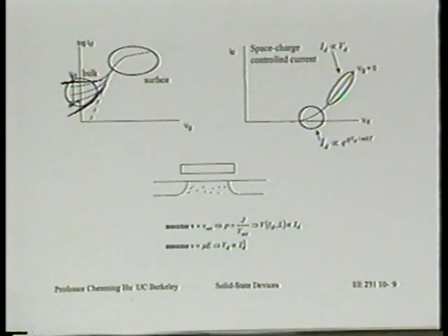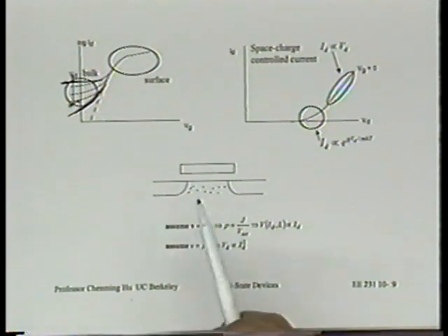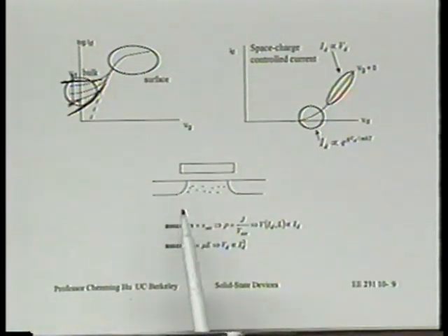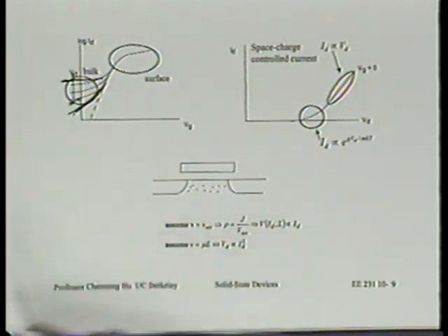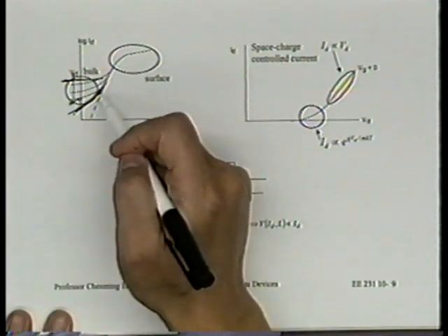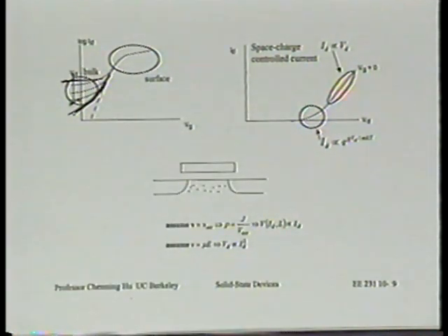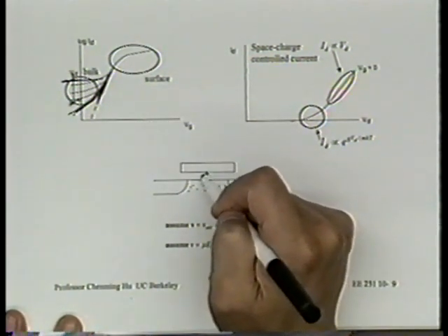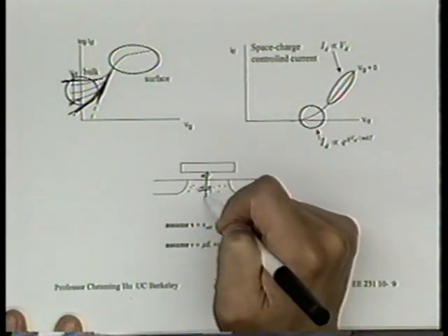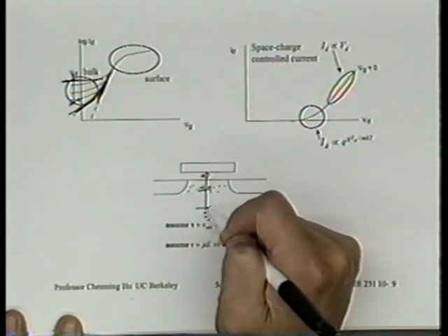And that's possible. I don't want to force you to think too hard about it, but if you can, maybe you can visualize a three-dimensional energy band diagram, not just plotting from source to drain. Anyway, I will not go on further. So this slope is a very good indicator of where the current is flowing, because the slope is determining, if you remember what determines the subthreshold swing. The swing is determined by the ratio between this capacitor and a capacitor that goes to the ground, namely to the edge of the depletion region.